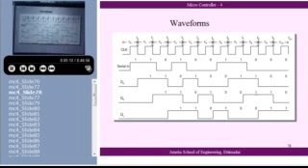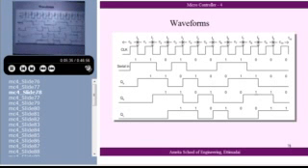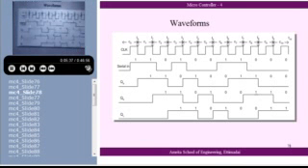QB, QC, nothing happens because as far as these are concerned, when the clock pulse comes, QA was originally at 0. QA was before that at 0. So nothing else happens here because it is at 0 value. Now, at the next clock pulse, this is 1. So this becomes 1. Alright?